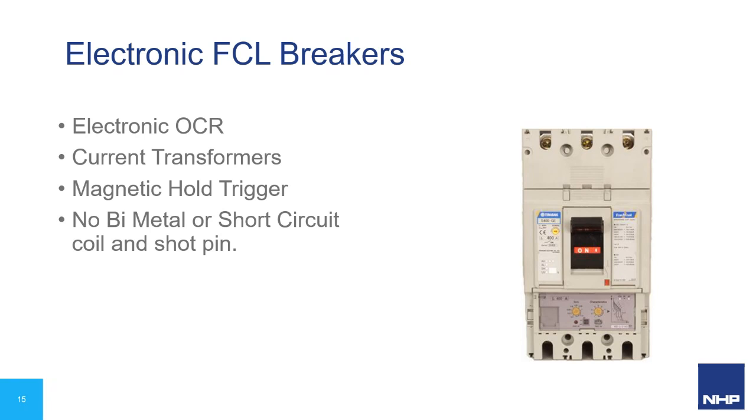So this is the characteristic of the type B MCCB. A very small time delay, in milliseconds, is incorporated into the trip signal initiation. The type B are designed to allow for selectivity at a high level against type A or thermal magnetic breakers. In other words, the thermal magnetic breaker inherently has a quicker trip function under short circuit than the electronic breaker.